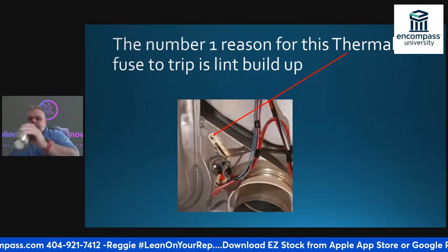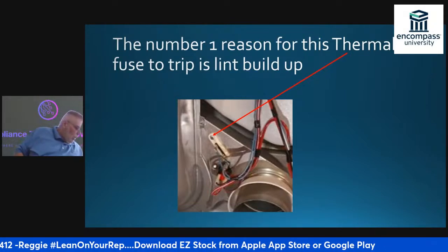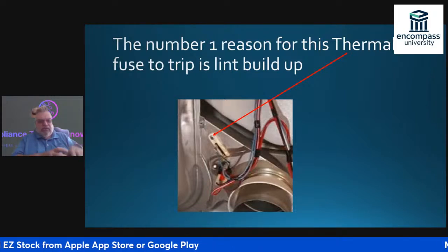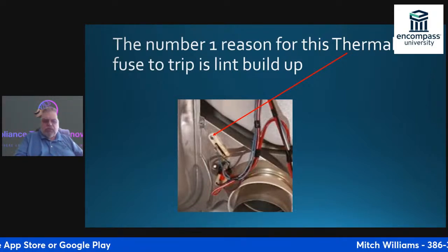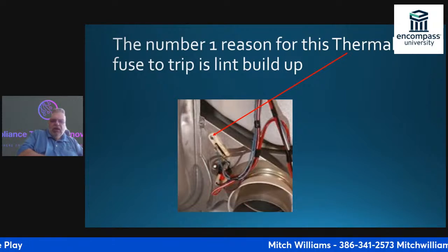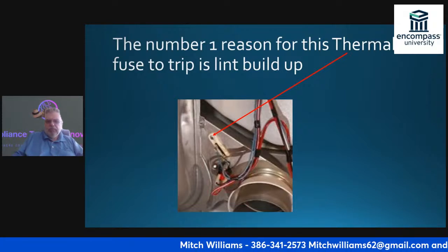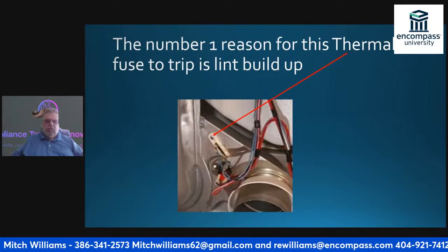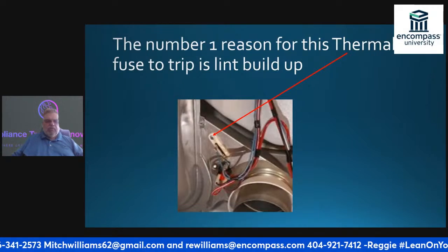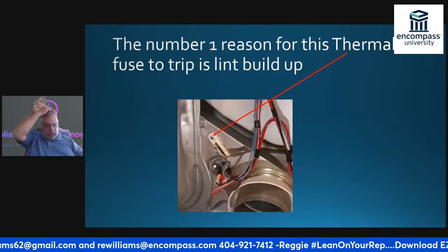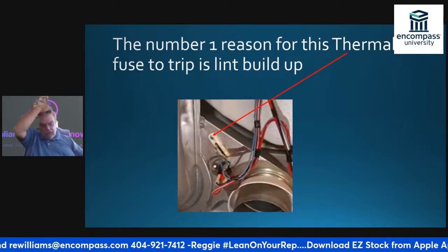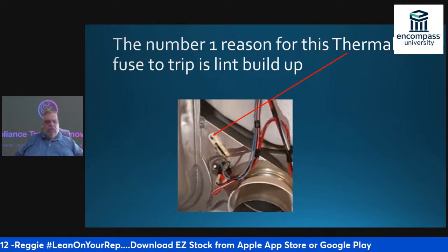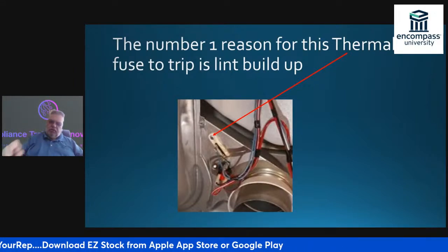So if I go in and I see that I have power to the plug, but nothing coming out of the unit and it won't start, I'm going to go to the thermal fuse. I'm going to unplug one of the wires and go across the thermal fuse. Actually, just go ahead and unplug both the wires and then go across the thermal fuse. Put your meter to the lowest setting.